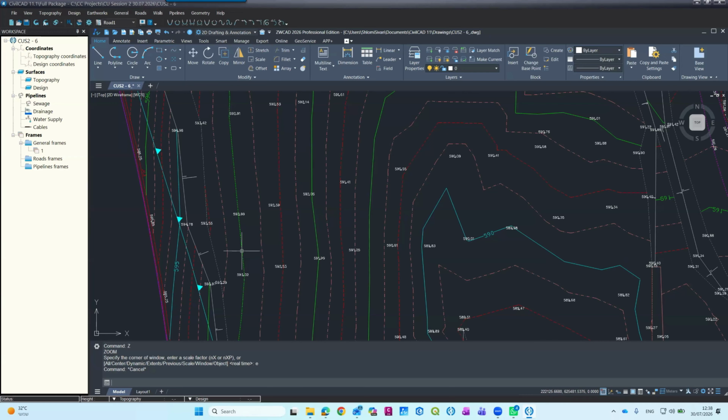So what I'll do, I will do some kind of reverse engineering. I will take this DWG and convert it into a coordinates list. And based on this, I will create my surface. Let's see how to do it in action.